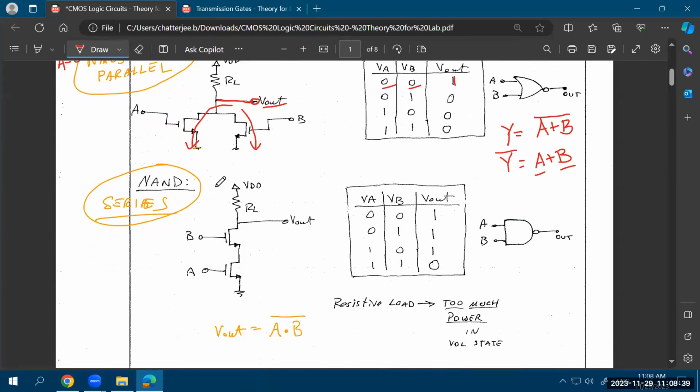On the other hand, if it is a NAND logic or an inverted AND logic, your output is equal to 1 when any of the inputs is 0. When both the inputs are equal to 1, your output is equal to 0. So that's the definition of a NAND. And the symbol of the NAND is over here. The symbol of the NOR is over here.